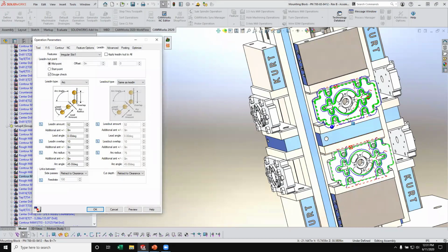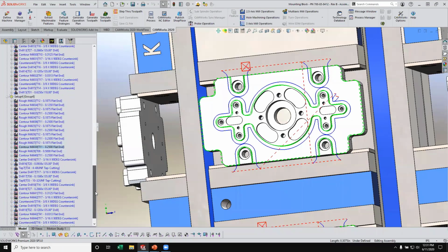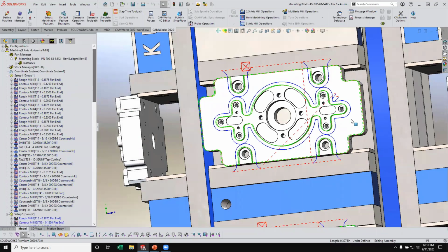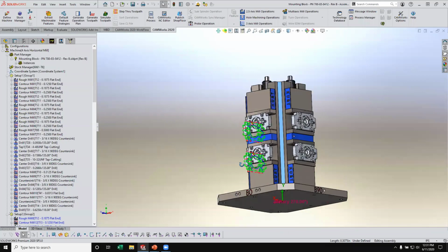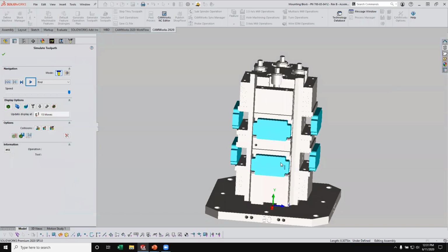So I'm going to change that point here, we zoom in, there we got it, the blue dot moved, and I just hit F5 on my keyboard, and that regenerates the tool path, aka previews it. I'm going to go ahead and OK that. So that went through and fixed that issue in every instance. We're going to kind of go back and simulate this again on just that first setup and see if we got anything else going on here.